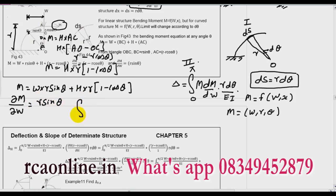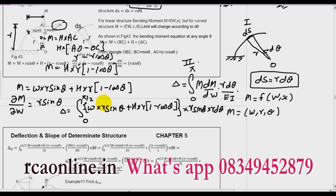Now as per the Castigliano theorem, what is my delta equal to? Integration 0 to pi by 2 of M. So M is W into R sin theta plus H into R into (1 minus cos theta). This is my M. And what is my del M by del W? It is R sin theta. Then in place of dx, I will place R d theta, over EI. If you solve this integration, you will get delta. This is the way to find the vertical deflection of the curved member.